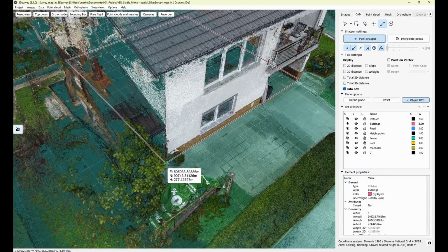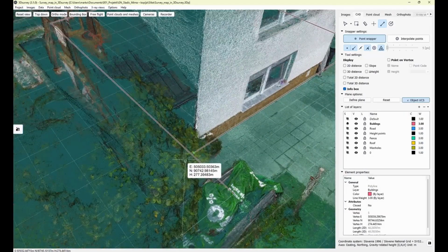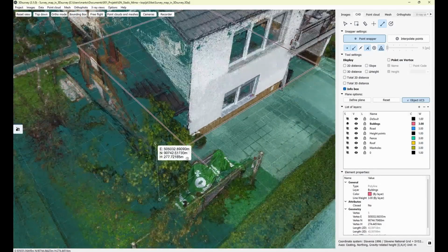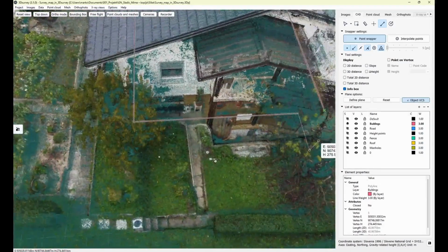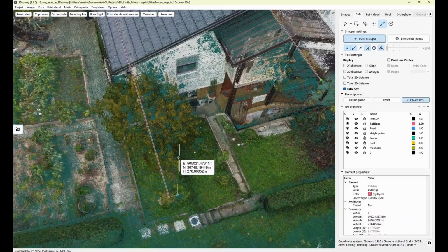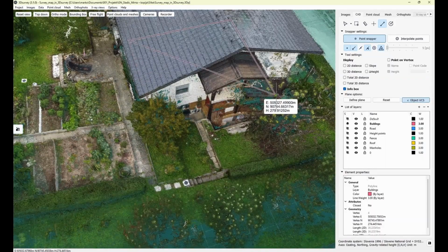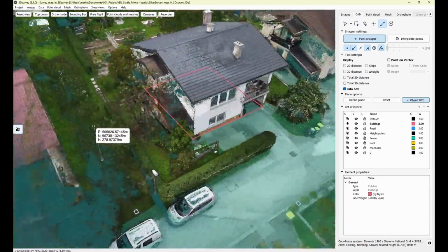And if my building is not perfect, I can snap on my last point like so. If I'm sure that my building is perfect, I click one backspace to delete my last selection, and then activate my snapper by moving to the end point of this line. Now I get the perfect suggestion where this line should end, and I just click it like so. Now I have perfectly added it.